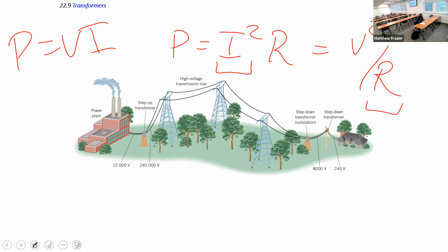No. Do you remember we had the circuits, right? Let's say we had a bunch of bulbs in parallel. What you notice is that the bulbs nearest the battery were slightly brighter than the bulbs furthest away, and that's because there was more wire in the path. And so there's a slightly higher resistance.